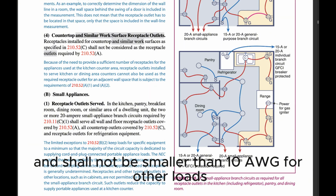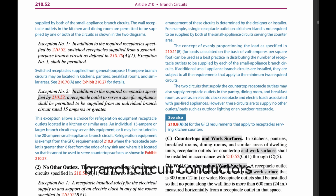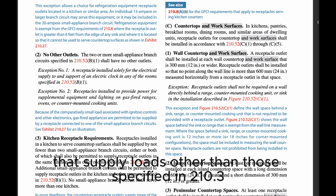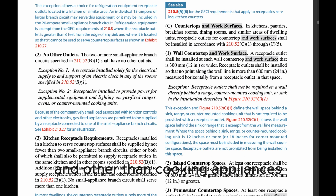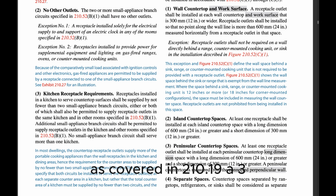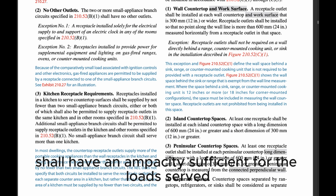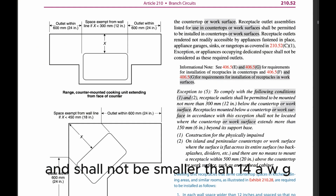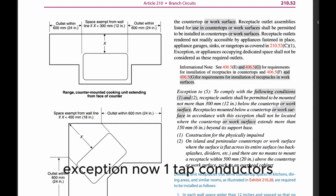(4) Other loads. Branch circuit conductors that supply loads other than those specified in 210.19(A)(2) and (A)(3) and other than cooking appliances as covered in 210.19(A)(3) shall have an ampacity sufficient for the loads served and shall not be smaller than 14 AWG. Exception no. 1.